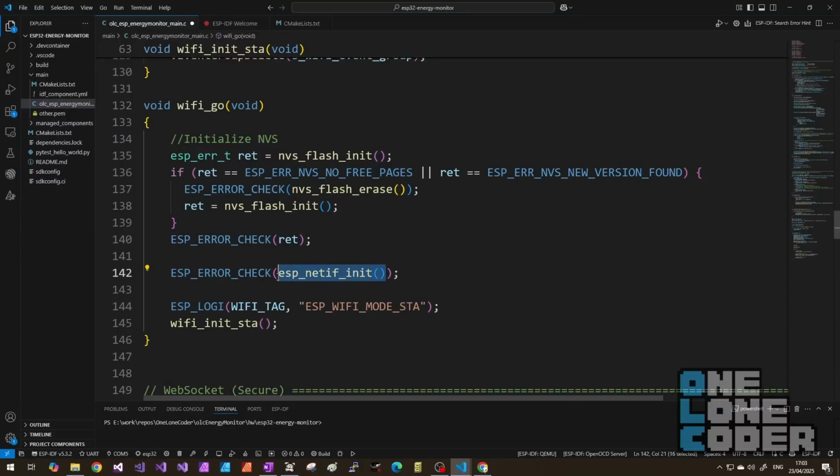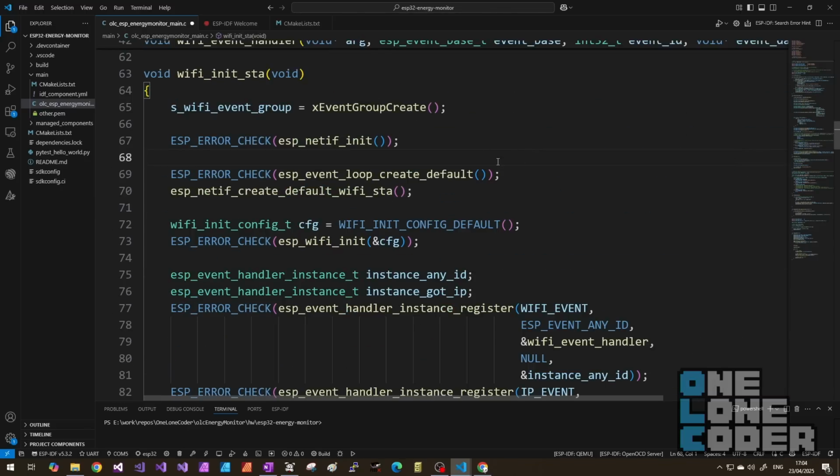We then need to initialize the network stack. This is the stuff that handles the TCP/IP lovely goodliness. Finally, we initialize the Wi-Fi itself. We'll have to have a look at this function. Don't forget we're running a real-time operating system, so we can shove things into tasks to just sort of happen in the background. This is necessary in an application like this, so we're not blocking things all the time. And connecting to Wi-Fi and things that are unstable may require several attempts or searching or at least tuning in, none of which can be done in a deterministic amount of time.